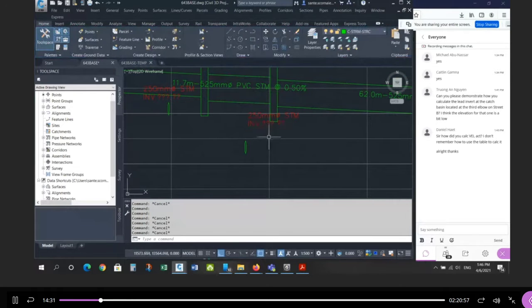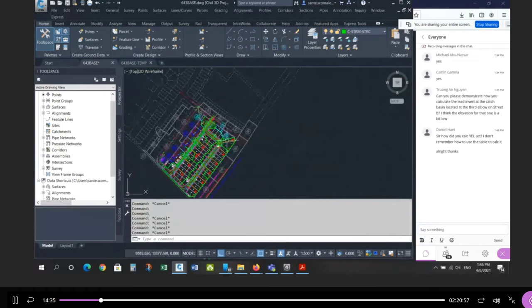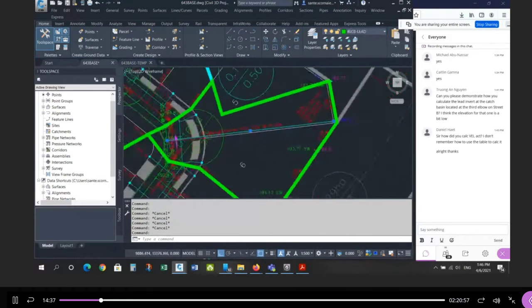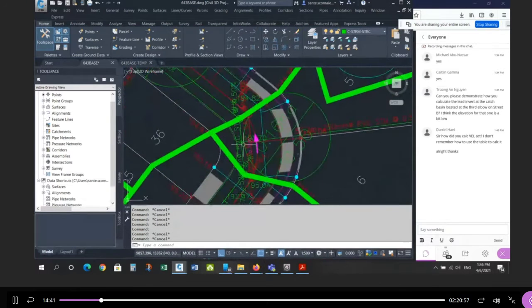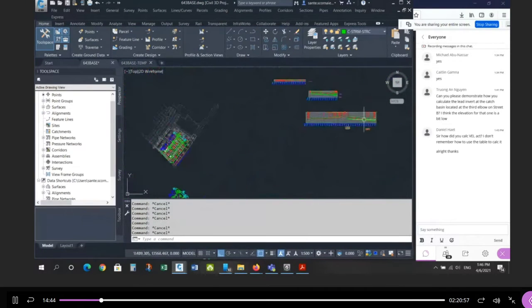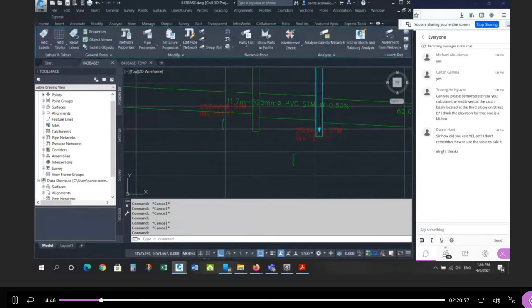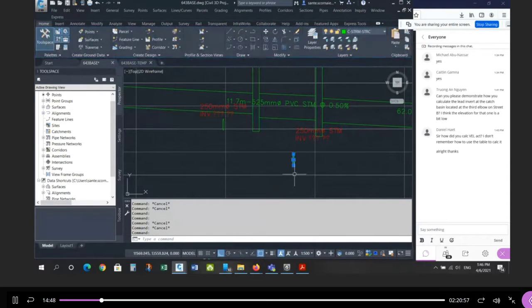This is the corner one. So if you look at the site, this is the culprit. This is the longest lead. It goes down the deepest. And it'll be between those 2 maintenance holes. It's connecting to the short pipe. So you'll see here it's between these 2 maintenance holes, and it's way too low.